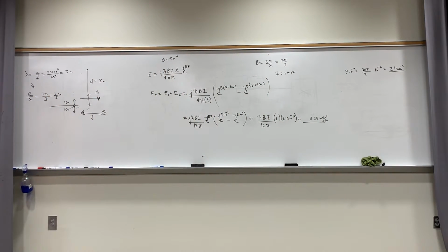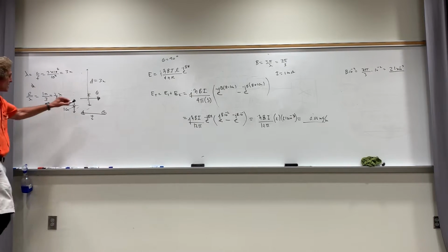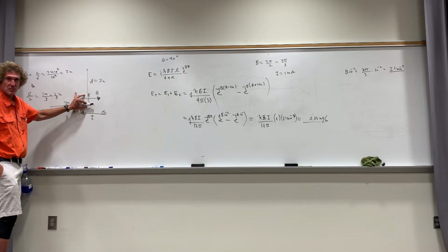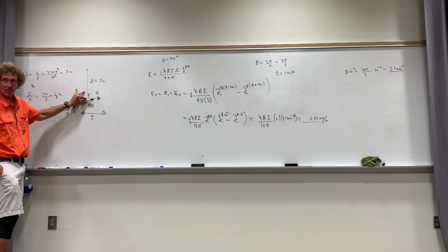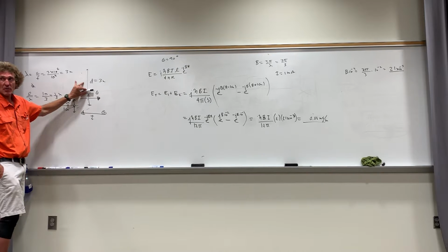If I gave them a test and didn't go through this with you, I can almost guarantee that somebody's going to mess this up in a royal way, not just a little, because I see this all the time. Agreed? There are going to be distances above a ground plane, as you move this antenna, where you get perfectly constructive interference, where the electric field will be double that of just a single short dipole. And then there will be regions where it'd actually be zero. You follow me? Because you'd have perfectly destructive interference.